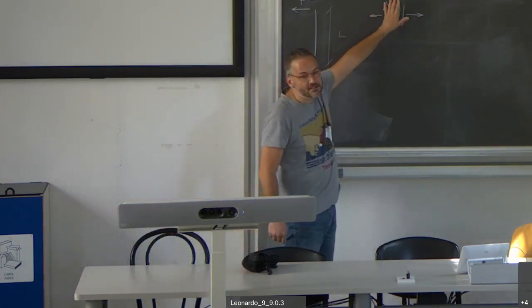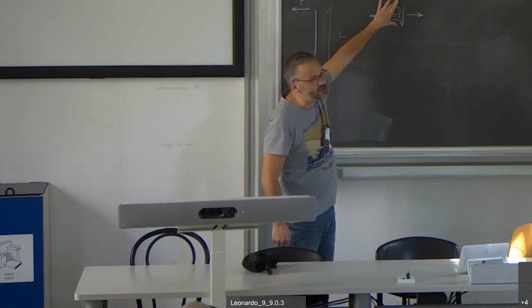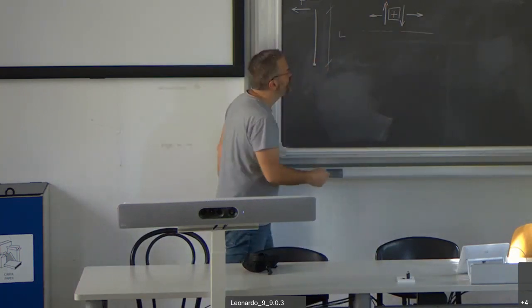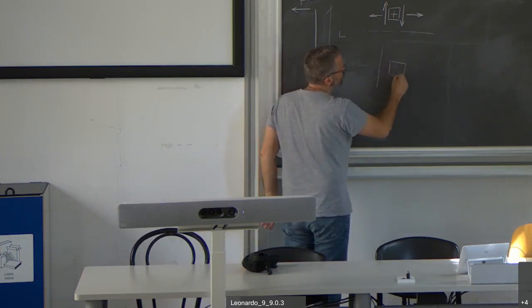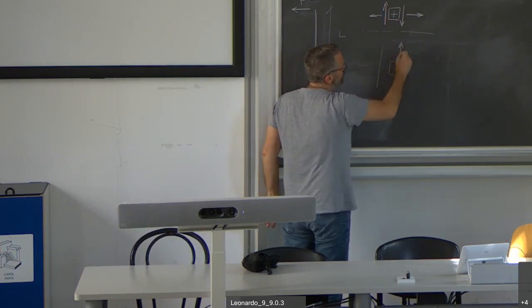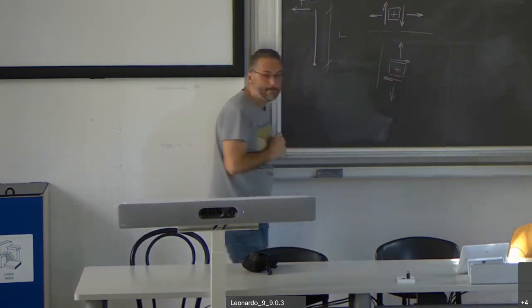So now I take this. This would be the element for the conventions if the member was straight and horizontal. If it's vertical, it means I have to draw my conventions like this. I will simply rotate it by 90 degrees. Tension means this. Clockwise means this. Okay?